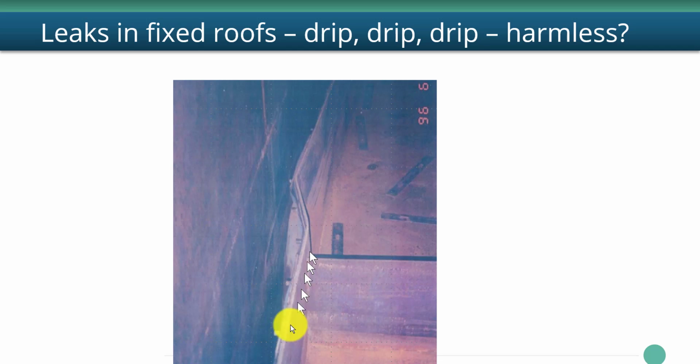This is a steel pan, a bulkheaded pan roof. It doesn't have the covers, it's just an open top. And again, this is a corrosive environment because it's a low point. There are cases where this roof has sunk because leakage from a geodesic dome, the dripping has caused corrosion holes, and then these pontoons filled up with liquid.